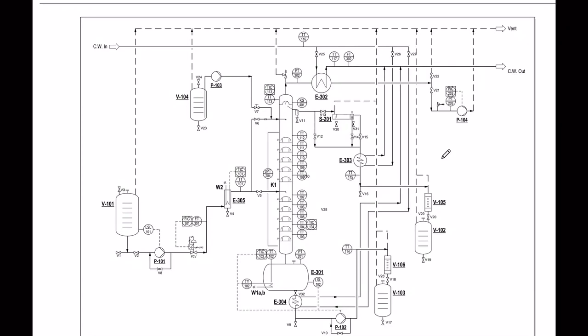Okay, then when the top column temperature sensor TT113 as well as the bottom sensor TT102 show a steady state reading, you can record the temperature at each tray, top and bottom column, on the control panel. Then you can collect a sample product at the top, which is V11 or V16, as well as the bottom at the V9, and you have to make sure that all the remaining liquid in the sampling valve V9, V16 as well as V11 are removed.